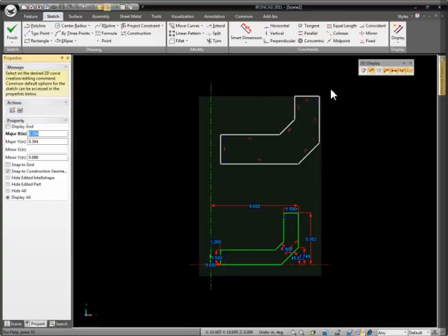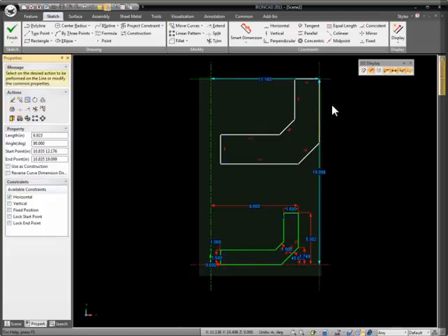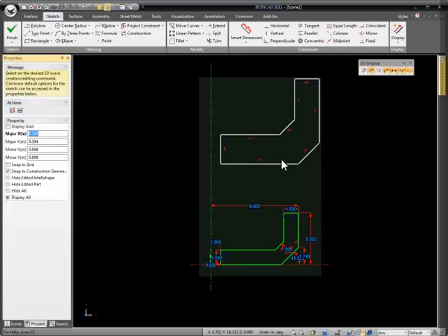And it's actually smart enough not to over-define your geometry. Notice both the perpendicular and the horizontals did not turn on. One or the other will turn on by default depending on your geometry. So you can, by default, automatically constrain your geometry to give some intelligence on how your curves will move based on how you created it. This is basically a user preference, whether you want these elements to automatically create or not.